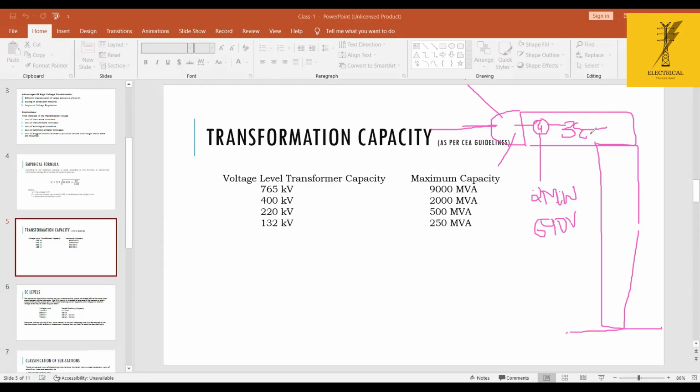This is the transformer. The rating of the transformer is 2.35 MVA, and it is a dry type transformer which steps up the 690 volts to 33 kV, and this 33 kV comes to the bottom through a cable, and we have an SF6 circuit breaker here, and this cable is a 3-core 185 square mm cable that comes out. So the whole design, maintenance, testing and commissioning, erection, everything of this wind turbine will be in the scope of the OEM only, the manufacturer, like Siemens Gamesa or Suzlon or maybe Vestas. These are the main players in these wind turbines. They build everything, and they will give a 33 kV, 3-core 185 square mm cable as the output. So from this cable, our design work will start.